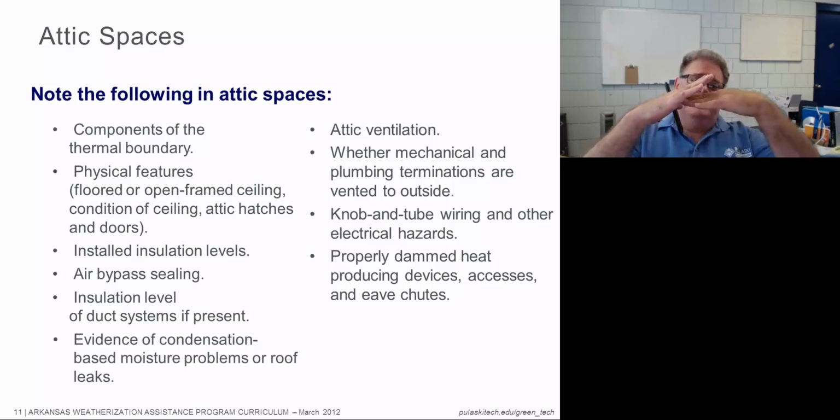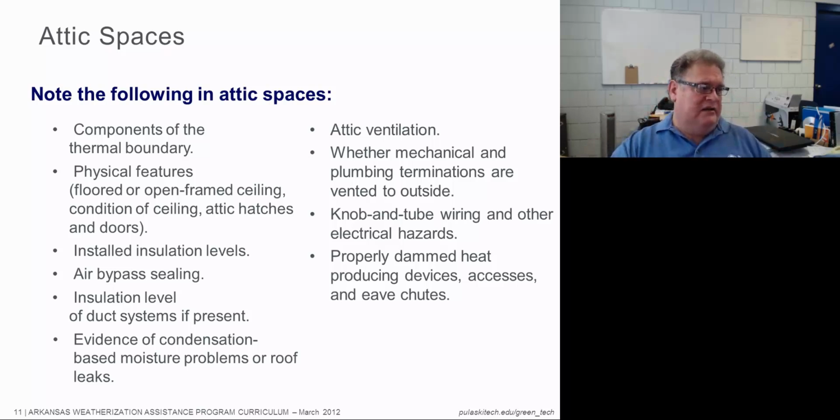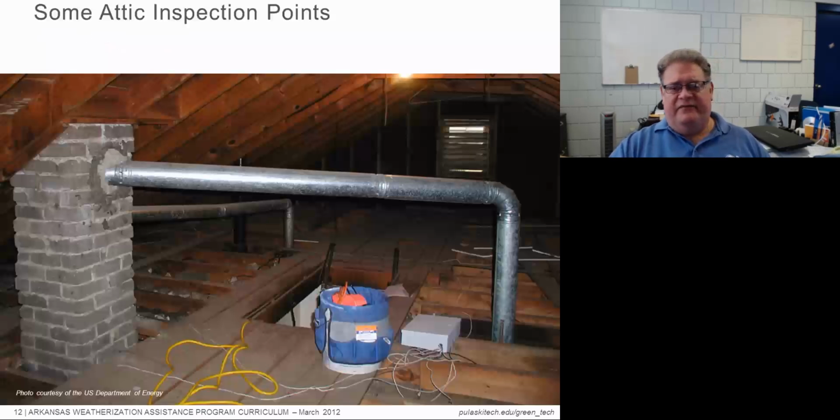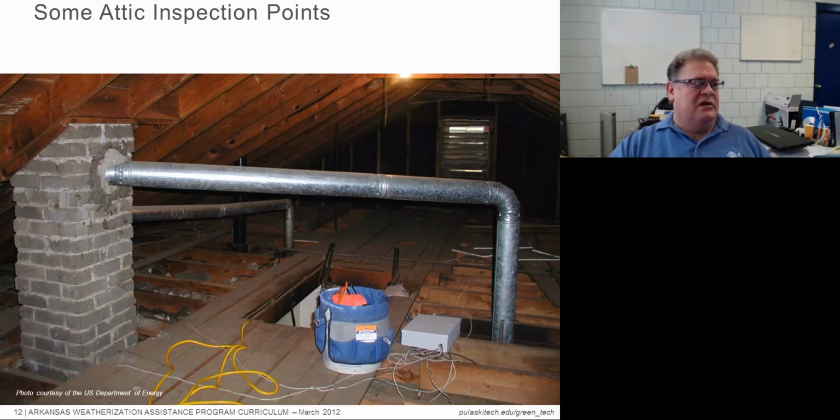We don't want the insulation to come up so high that it cuts off the air path underneath that roof deck. So we'd put a chute in there, and then we may put a dam at the end of the top plate to prevent insulation from moving into that eave area back in the very corner there and blocking the air path for our ventilation system on the attic.